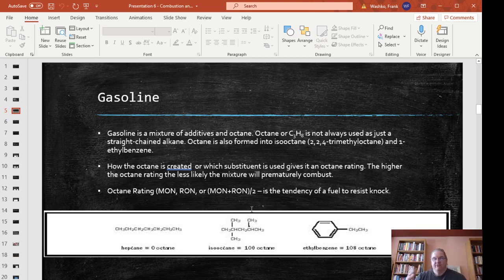A higher octane fuel requires more energy to be put into it before it combusts, and that too is part of the reason why. I'll get into that, but let's say a lower octane fuel is more combustible. It's more volatile, such that if you use a lower octane fuel, we talked about this idea of knock. So if you take the air fuel mixture and you put it under a compression ratio of